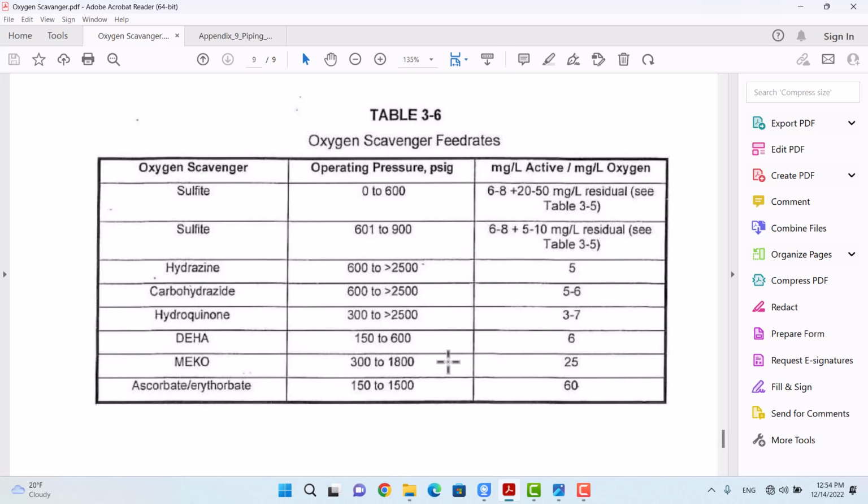But in order to make sure that in terms of performance, in terms of passivating agent, in terms of oxygen level in the system, it has been really great, because we have laboratory tests and field tests. We conduct this kind of laboratory tests daily, in night shift and in daytime, and in all of these situations, while using DEHA as an oxygen scavenger, the level of oxygen has been extremely low, and we have been extremely satisfied with its performance.